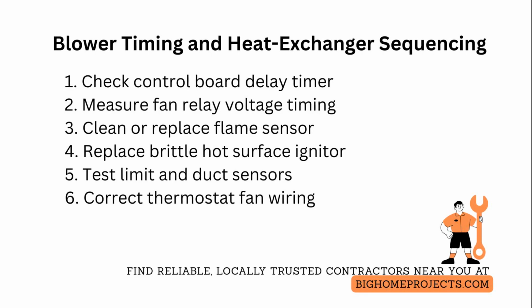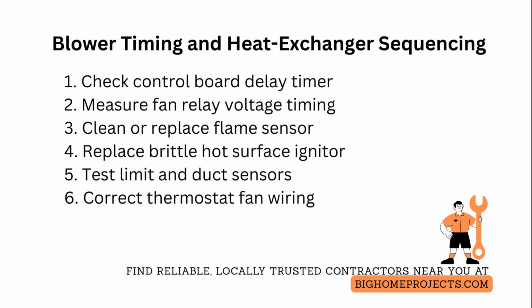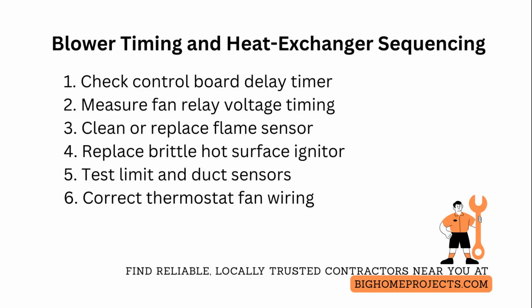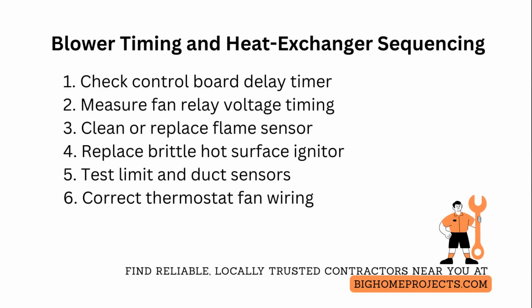Inspect the flame sensor and ignitor condition next. A dirty or weak flame sensor can cause the control to misread flame presence and either prematurely allow the blower or cycle the burners. Gently clean the rod-type flame sensor with fine emery cloth and reseat it, and replace a brittle hot surface igniter rather than risking intermittent ignition.